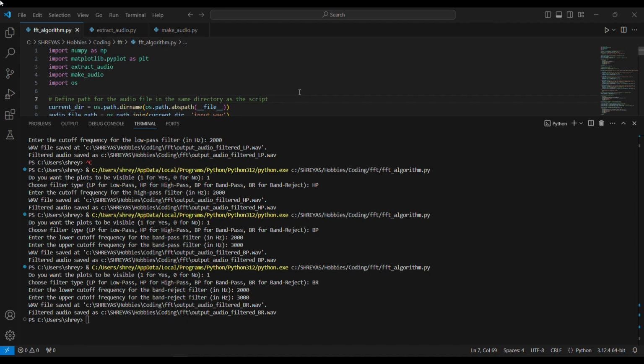A real-world application of these types of filters for sound processing could be in songs. For example, if I have a song where I can hear a very high frequency which is kind of annoying to me, what can I do to reduce that frequency to make that sound more pleasant to me? I can apply a low pass filter or a band pass filter on that particular frequency component which I don't need in my sound.